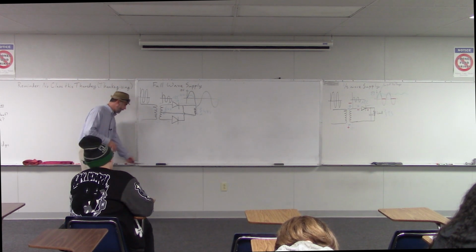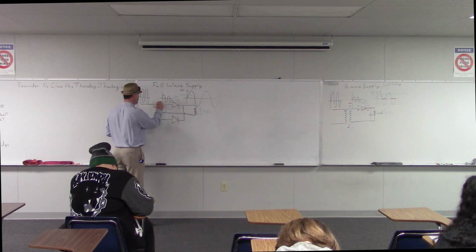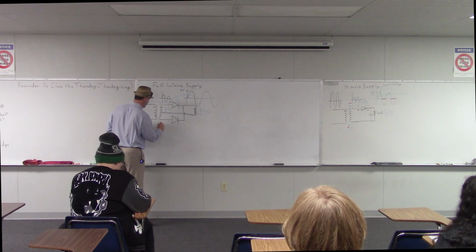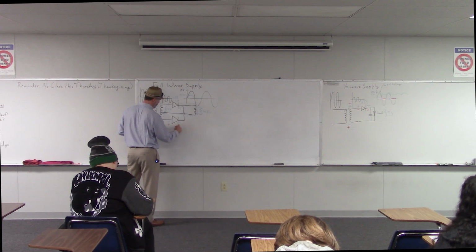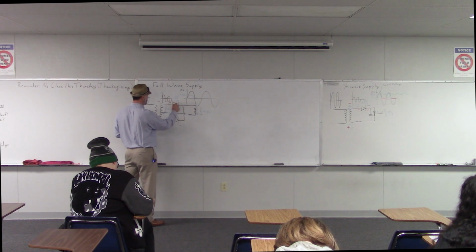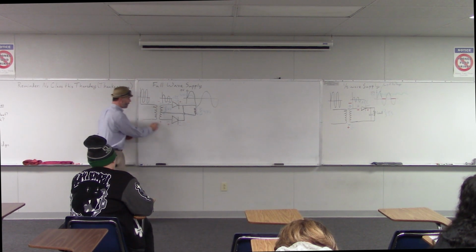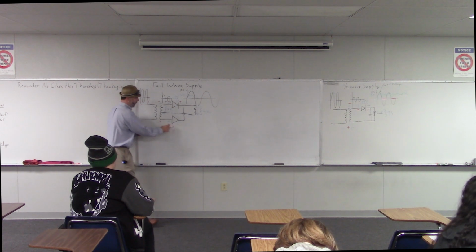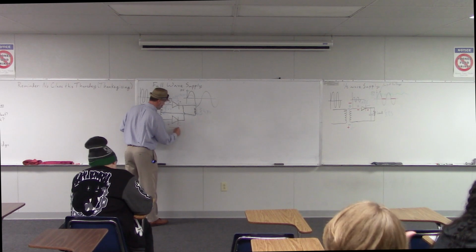All right, so then we can look at what happens in the opposite case when we have a negative voltage at the top and a positive voltage at the bottom. So now this bottom diode has a positive voltage there, negative there. The top one has negative and positive. So is this bottom diode forward biased or reverse biased? Forward, exactly. So the electricity flows through in that direction.